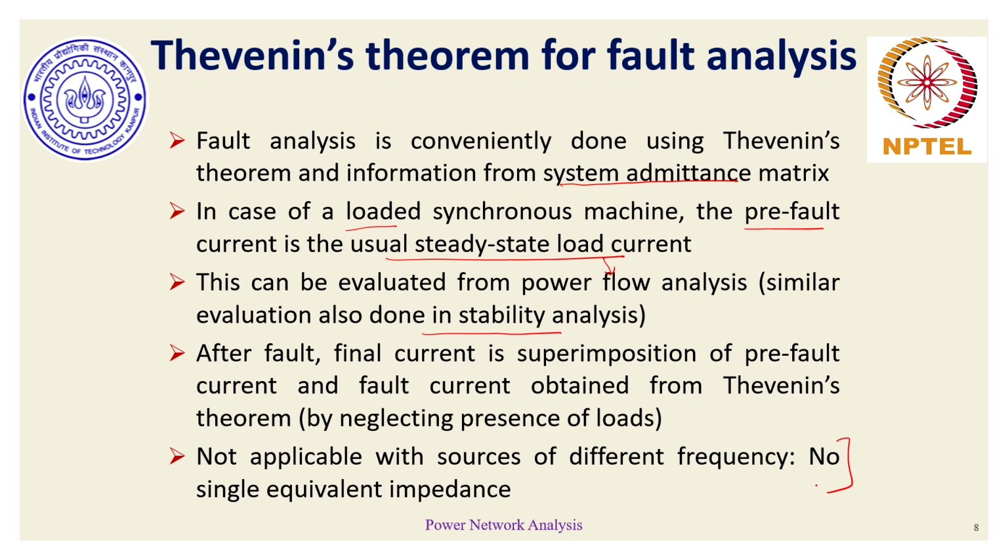Remember, Thevenin's theorem is applicable only for a circuit with sources of the same frequency, because it heavily depends on evaluation of Thevenin impedance, which is in a phasor domain representation, and phasors cannot be defined for circuits where there are two different source frequencies. So that's the reason why Thevenin's theorem is not applicable for sources with different frequencies.